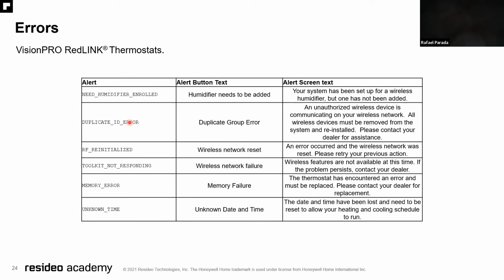That is not going to happen. It's not compatible. So what we recommend is to make the connections individually, connecting first the Prestige to the EIM that it belongs to, and then connecting the Vision Pro to the EIM that it belongs to. If this was a new installation, we recommend to purge all the devices and connect one by one.